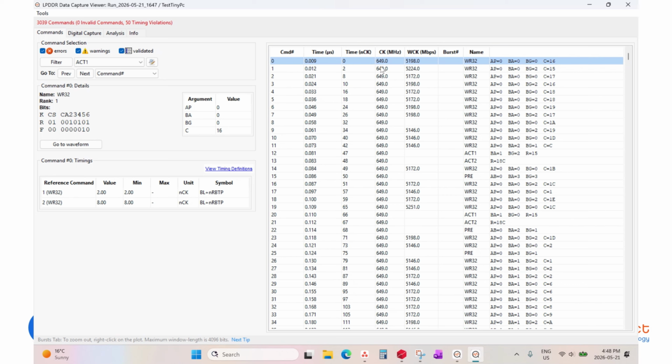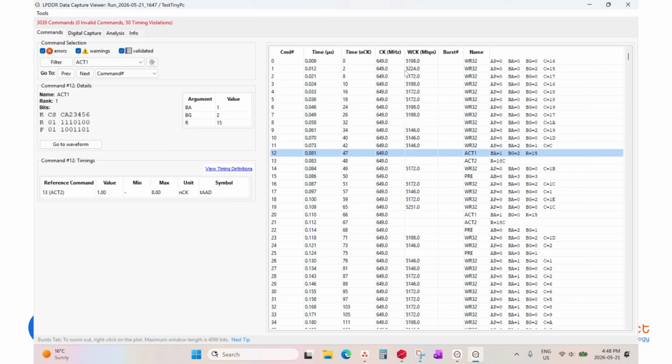And the reason is that the analyzer is always actually monitoring the traffic in hardware and understanding the commands that are coming in. And when you trigger on a certain command, the analyzer just freezes that capture window around the command that it sees. So there is hardware processing that is happening here. And what the viewer is giving us is basically just a snapshot of the traffic that's been received by the analyzer. So in this case, again, we're seeing a section of write and write operations.